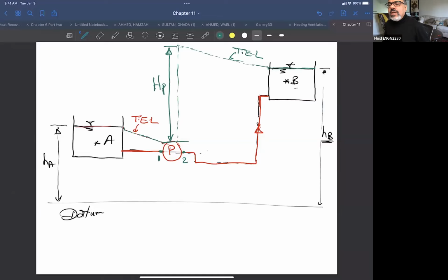Okay. Z here, I think people were talking about Z and potential energy. For a tank, this total energy is the head of the tank, right? At any point inside the tank, the total energy is a potential energy, or the hydraulic energy inside the tank. At any point here, the velocity is 0. This is pressure over gamma, and this is potential. So the total will be your line. This is your total energy line inside the tank, and it is horizontal because there's no motion inside, there's no losses inside the reservoir. But as the fluid is going inside the pipe, the energy will decrease because of the frictional losses and eddy losses and so on.